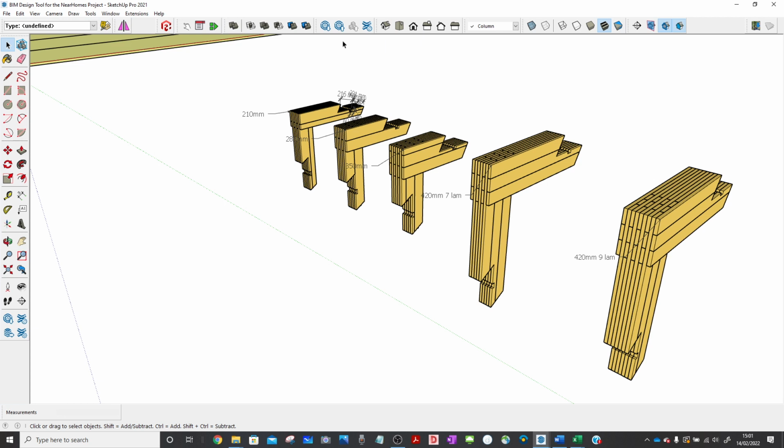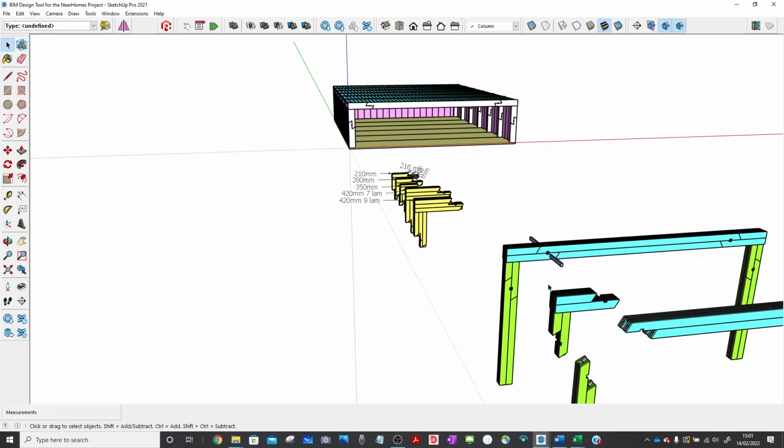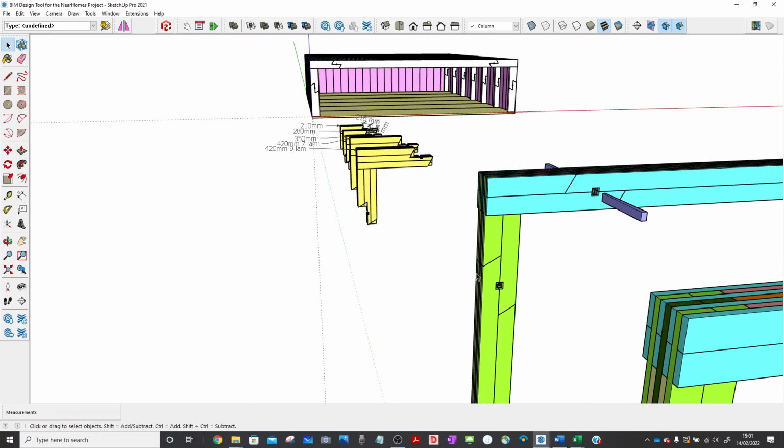Well, trees are the same. Timber is exactly the same. Timber, if that's my timber this way, it will compress quite easily that way. It will not compress this way very well at all. It'll be stiff. Because of the design of this connection, we found that the bottleneck wasn't the moment in this connection.